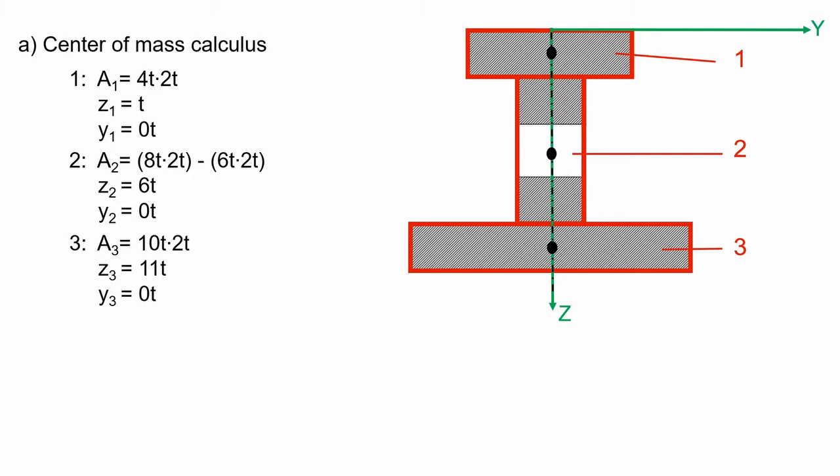Another important thing to mention here is paying attention when calculating the area of rectangle number 2. When there is no hatch in a cross section, that means we have to subtract that area from the geometric shape total area.